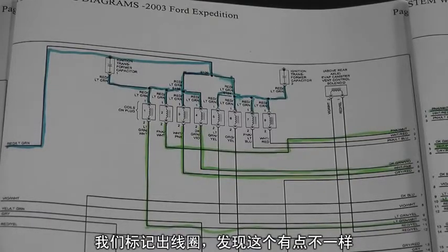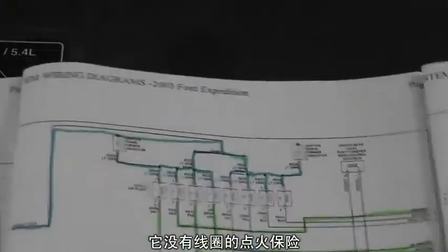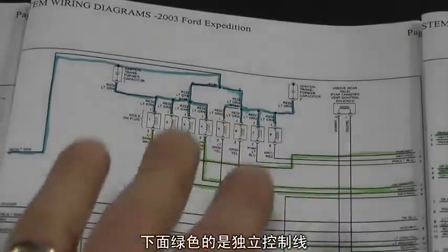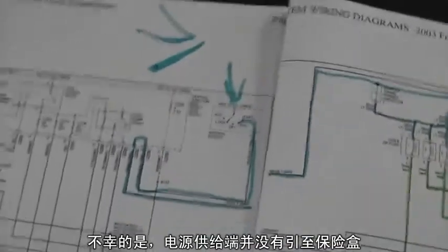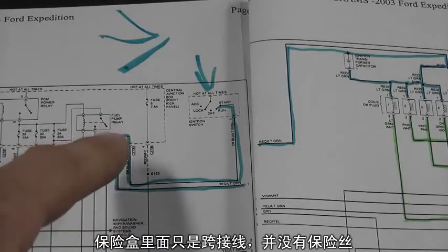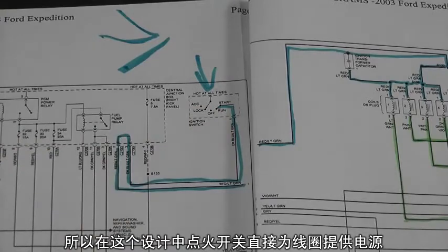We mapped out the coils, and what we found is this one's a little bit different. This one actually does not have a designated fuse for the coils. This up here that we have marked in blue is going to be our power feed for this circuit. The green circuits down below are going to be the separate control wires. Unfortunately, with our power feed, it does go to the fuse box, but inside the fuse box is just a jumper. There's no fuse, and then it goes right to the ignition switch. So the ignition switch directly supplies power to the coils on this design.